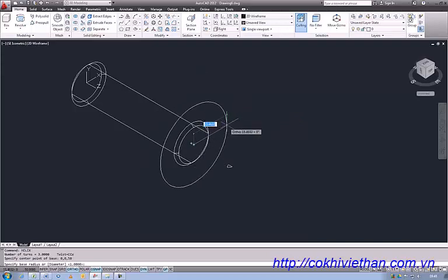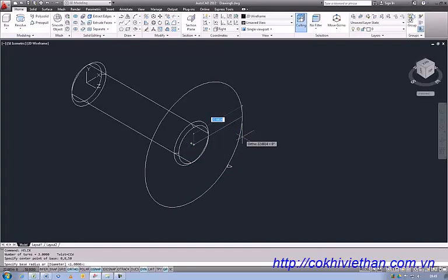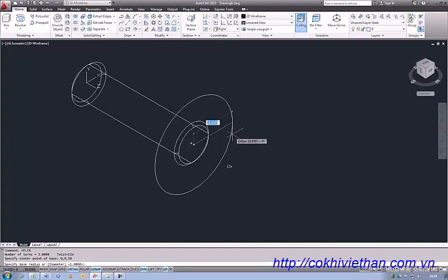Now if we look at the command line, or in fact as I move my crosshairs, I am getting the option, hold up, there it is, specify base radius. So that wants to be the radius of our bolt, which is 8mm, as it's a 16mm bolt.